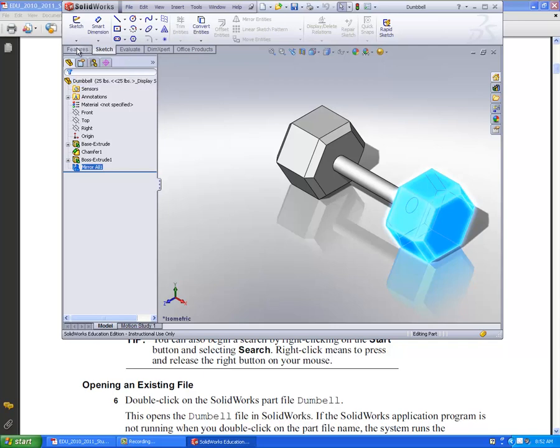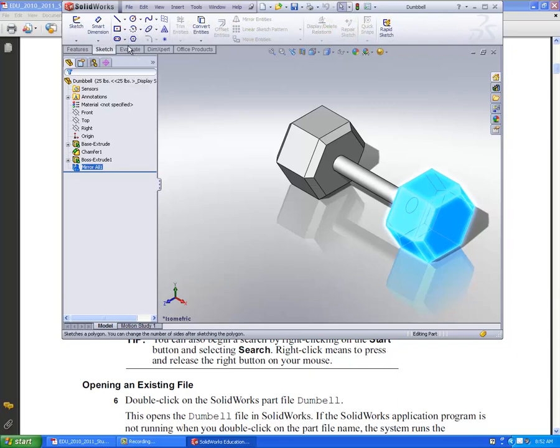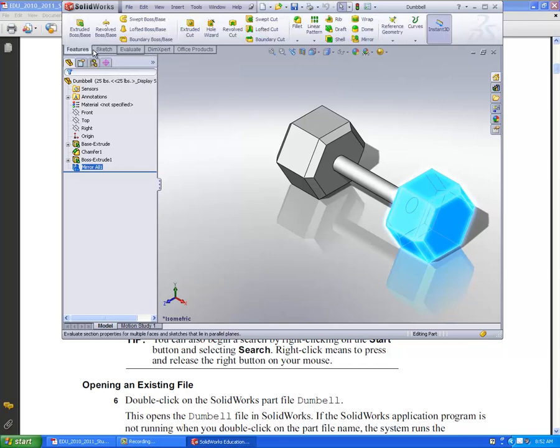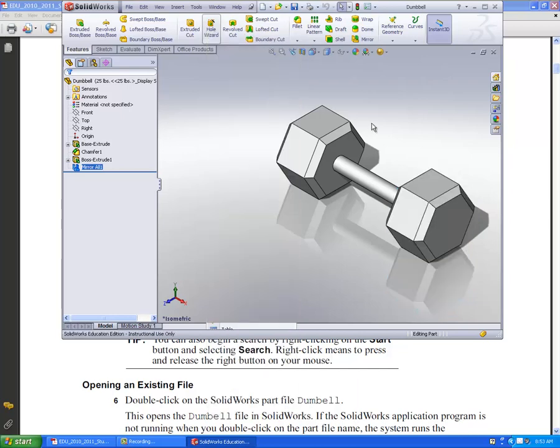This area right here is our command manager, and there'll be all types of actions we'll be using this for as we go through our different lessons. You'll learn what all of these buttons are for. Mouse button, we have our select on, so we can right click on any of these to do different things. And we can also left click over any of these to get back to a quick command.